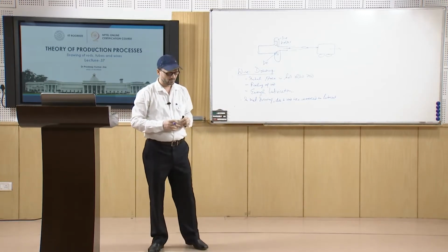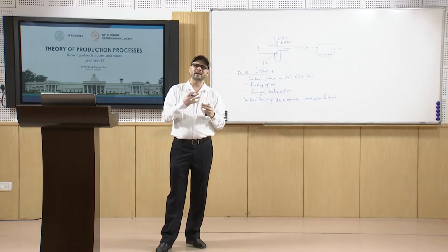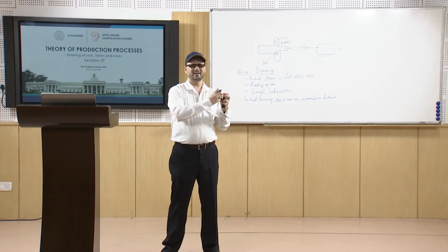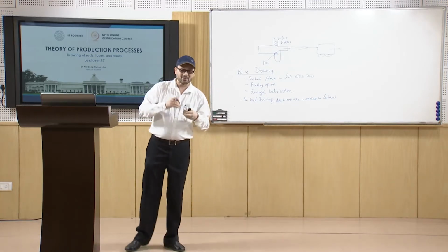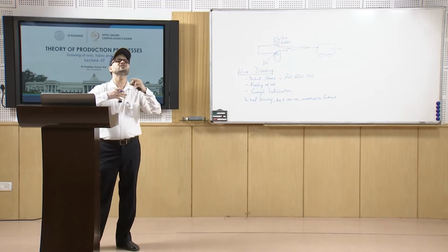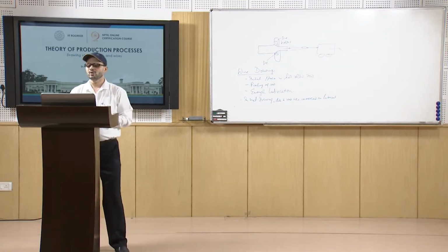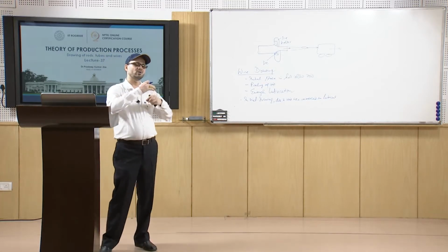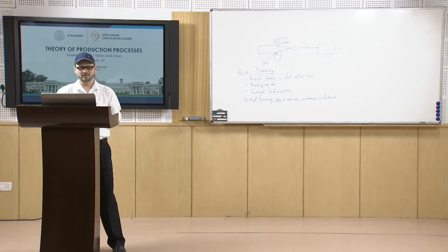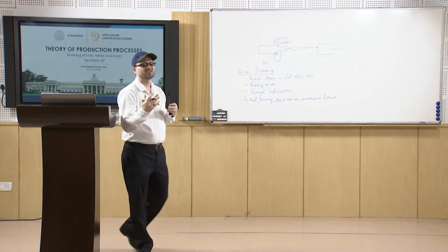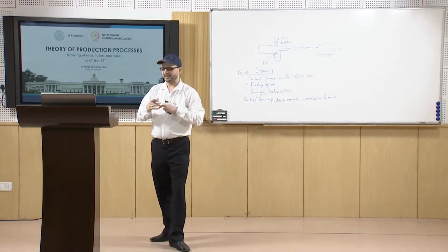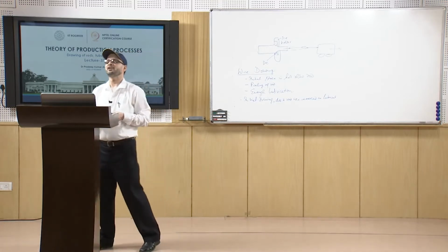So, that is how the practice is followed whenever we talk about drawing operations with large reduction, especially for wires. Now, what happens is that every time the diameter is reduced, the peripheral speeds increase. So, for avoiding any slippage between the block and the wire, the peripheral speed has to increase, and that is managed with the help of a motor mechanism many times.